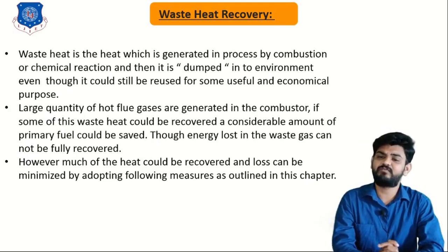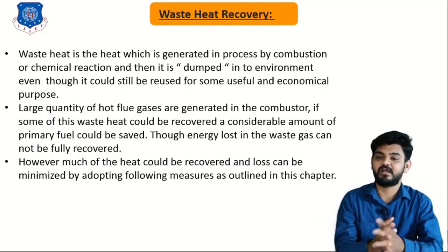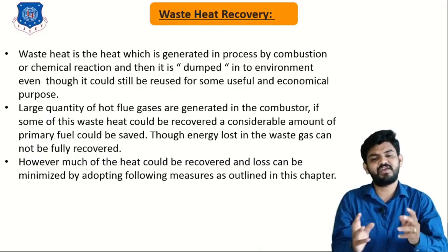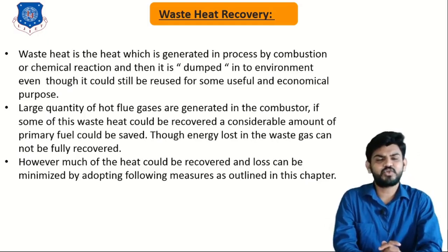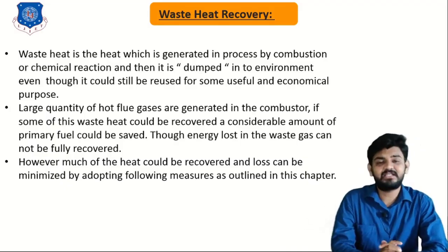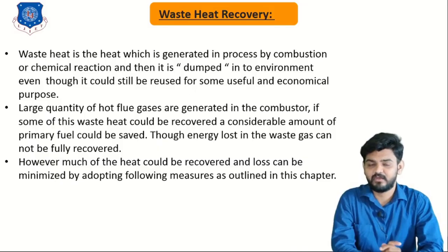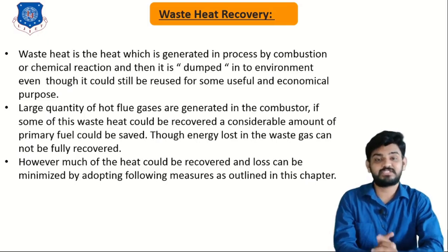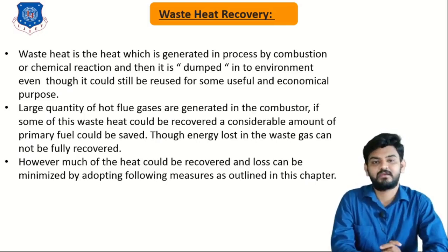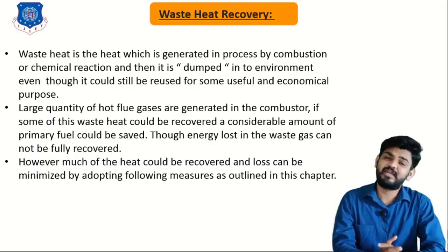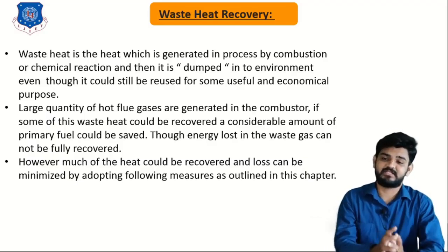Still, this heat can be utilized for economical and useful purposes. Such kind of heat we term waste heat. Large quantities of hot flue gases are generated in the combustor. If some of this waste heat could be recovered, a considerable amount of primary fuel could be saved, though energy lost in waste gas cannot be fully recovered. So large amounts of hot fluid are dumped into the environment and we lose the heat energy associated with such fluid. If we can recover this heat, we can achieve significant reduction in fuel consumption and increase fuel savings, even though we cannot recover the lost energy fully.